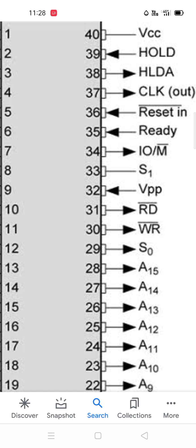Okay, now we have clock out. Clock out is for peripheral devices. They have to have a clock to run on, which frequency. Clock means frequency actually, and what frequency it is, what the voltage level is, and other things. That is why it is called clock out. So the microprocessor gives that particular clock to other things, and the clock can be varied within the other controllers, like an IO device and others. The clock can vary depending on what kind of input output is coming in. But this is the actual working signal that is given, about 5 volts.